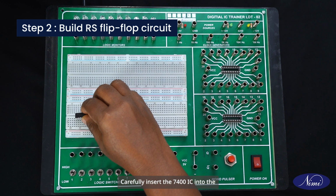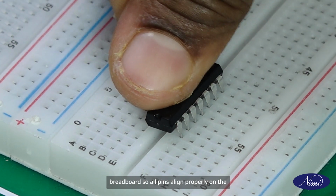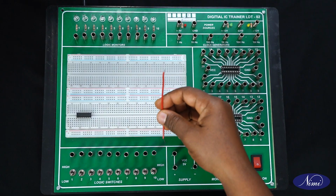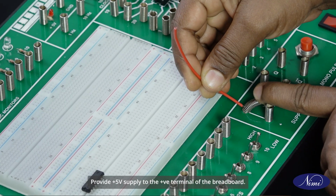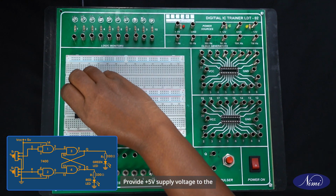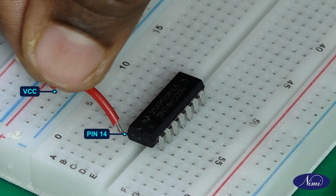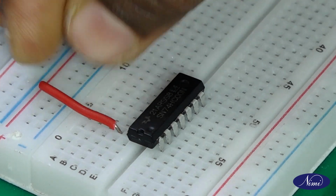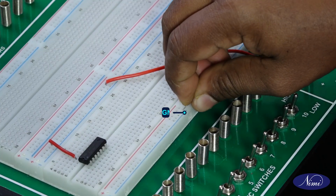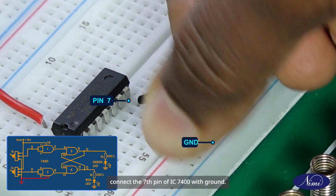Carefully insert the 7400 IC into the breadboard so all pins align properly on the power and ground bus strips. Provide plus 5 volt power supply to the positive terminal of the breadboard. Provide plus 5 volt power supply voltage to the 14th pin of the IC. Also, connect the ground to the negative terminal of the breadboard. Connect the 7th pin of the IC 7400 with the ground.